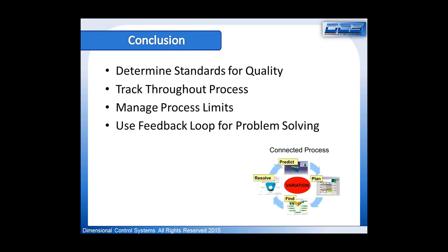So the conclusions, when we think about this idea of using data to drive process change and the effect of elements like springback, flex, and stretch, and combining process capability with the notion of deformable or compliant parts analysis, the idea is to start to create a capability that determines a level of standard that is not only driven by consistency in the part design, but consistency in the process, and consistency in the process that takes into account those things that are occurring in manufacturing that may not be apparent to design engineers, but are real world issues and